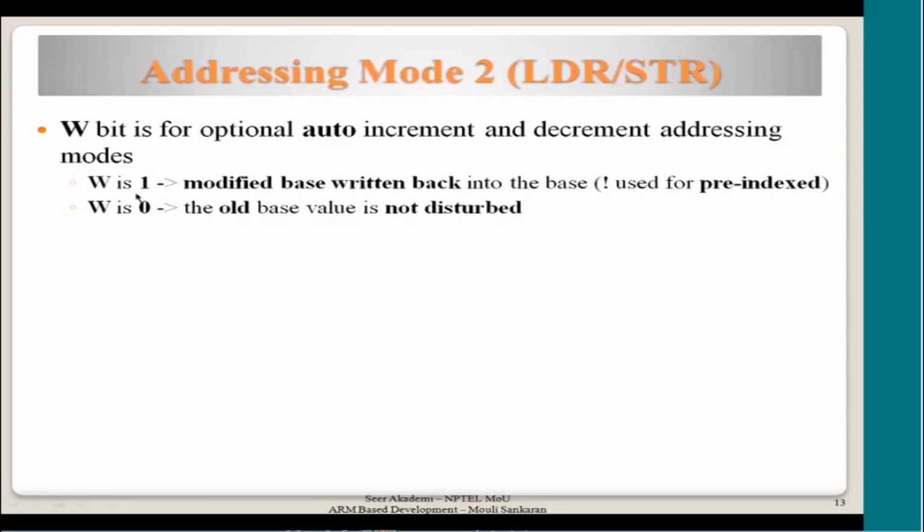If it is 1, the changed base address is written back into the base. That means you have mentioned this, and it is used only for pre-index. If you remember, in post-index you don't use it, but anyway it is assumed to be write back by default.